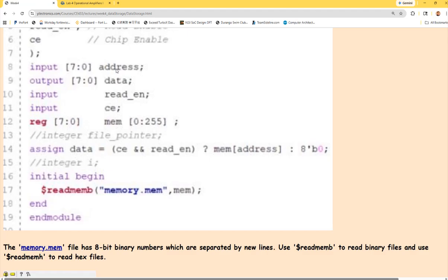So the data at certain addresses, but the memory is just a memory, right? Whoever is using the memory is going to tell the memory which address, which data at which address I want to take out from the memory. So it doesn't really have to care about that. It's just directly put address as an index in here, right? So no matter what address is being requested, it just directly put in here and take the data out at that address and make it available at the data output. Does that make sense? And that's it. It's pretty simple. That's it.